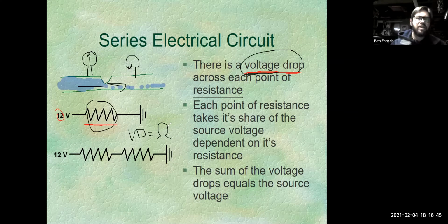Okay. So remember I said earlier, if the circuit is built correctly, I should not have any voltage drop or any resistance in the wire leading up to my component, or on the ground side going away from that component, right? My circuit should be designed so that I drop my voltage. I should have my resistance located in the component I'm trying to operate.